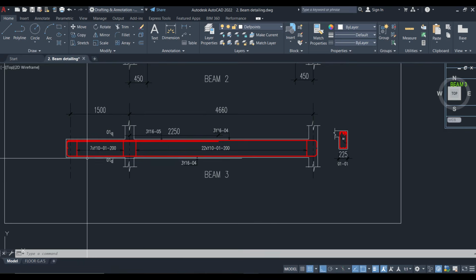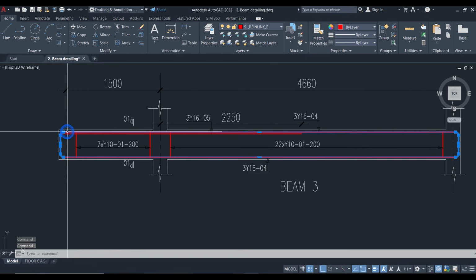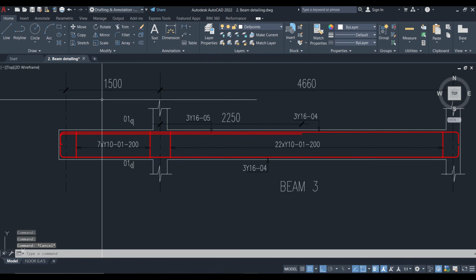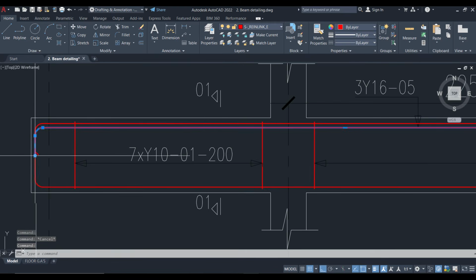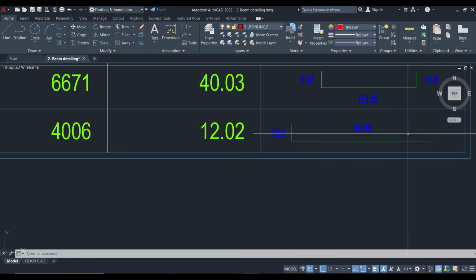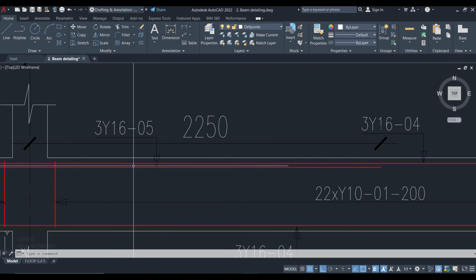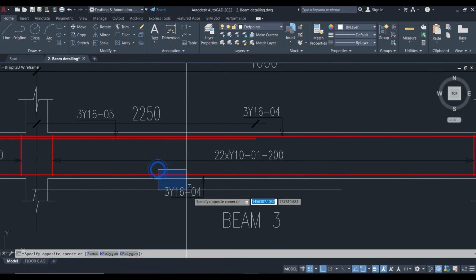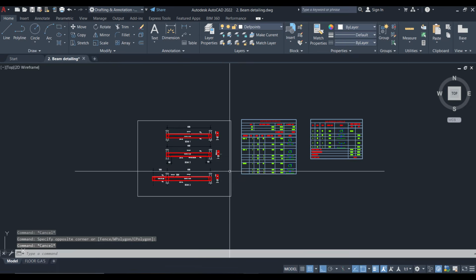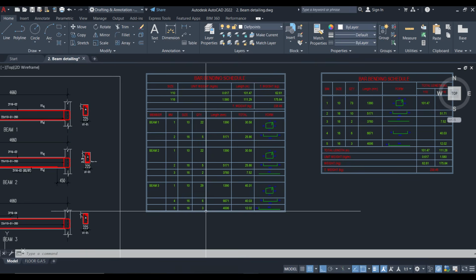For the longitudinal bars, we have two different bars. We have the same bar at the top reinforcement, but because this is a cantilever beam, it has a cantilever end, and there's an additional reinforcement at the top. This additional reinforcement has this shape. You measure the length and then the anchor. The total length of that additional bar is 316, and the bar mark is 5, while the bar mark for the longer longitudinal reinforcement is 04. So we make the records, and at the end of the day we have our bar bending schedule.